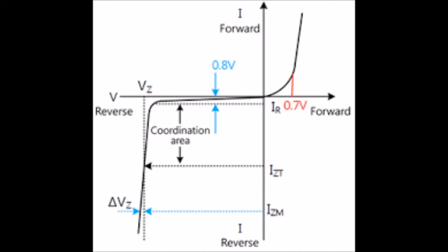A Zener diode exhibits almost the same property, except the device is specially designed so as to have a reduced breakdown voltage. By contrast with a conventional device, a reverse biased Zener diode exhibits a controlled breakdown and allows the current to keep the voltage across the Zener diode close to the Zener breakdown voltage.